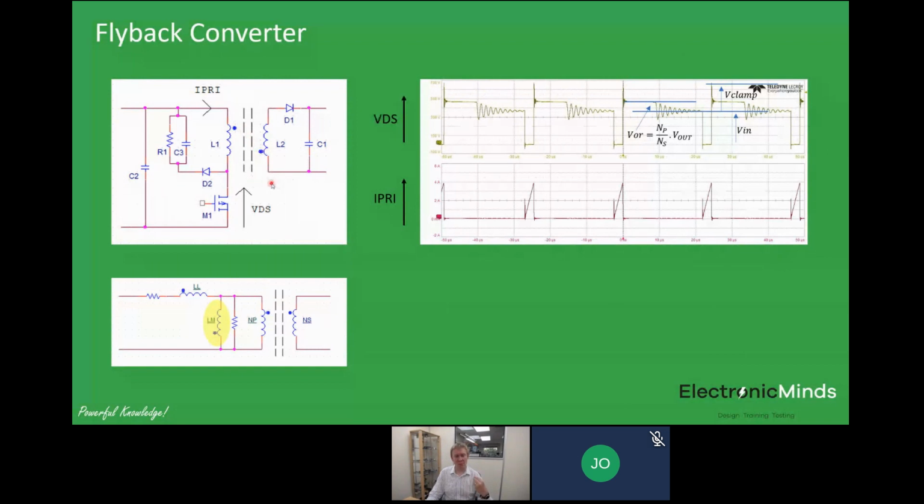The way a flyback converter works is, you can sort of see it from the waveforms here, but I'll explain it generically. When MOSFET M1 switch is on, the dot polarity of our windings here means that the output diode is blocking. So during the on time of that primary side MOSFET, the secondary circuit is completely out of circuit. And all that happens is you just start ramping up current in your magnetizing inductance and leakage inductance as well.